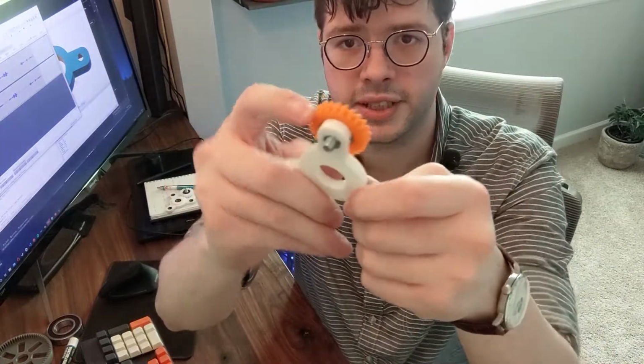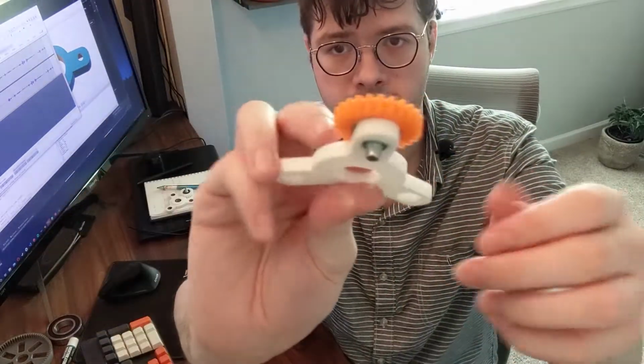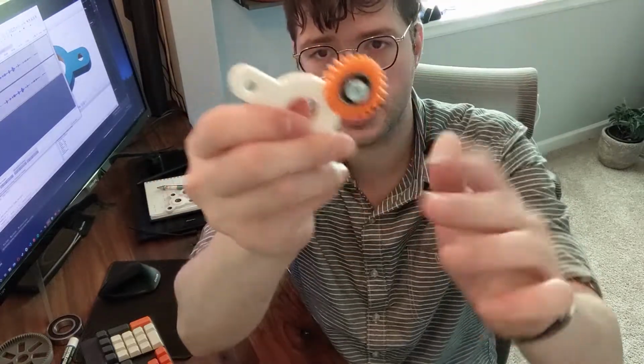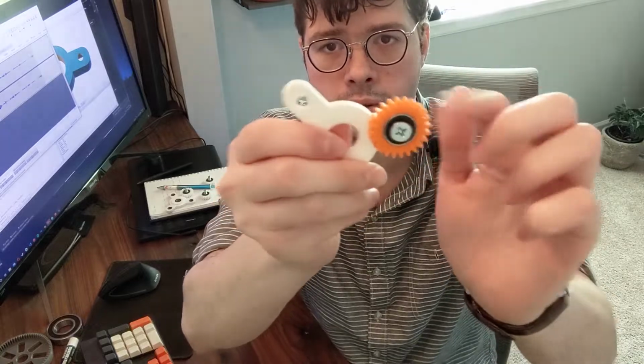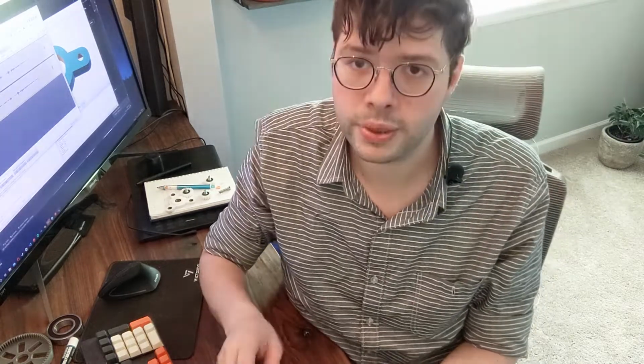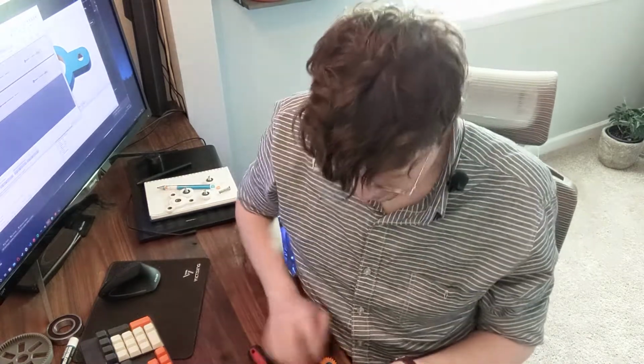We have it affixed. Now, the very first problem that you're going to run into is the fact that although it is very strong and affixed, I cannot very much rotate this gear easily. It has no movement because it's too tight. This has to do with how bearings work. You have to make sure that the inner ring and the outer ring are not fixed to each other. So that brings us to design consideration number 2. How do we make it such that the bearing can move freely?